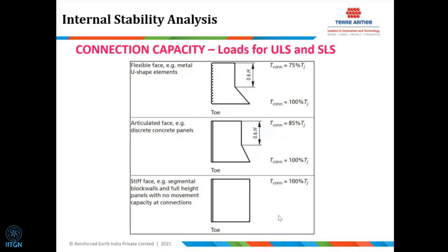because the behavior of the soil when we are doing the construction differs, as soil is not uniform around the world. The tests on which the coherent gravity method was developed, I'm sure they used a very nice soil, very good, and there is no doubt. But when we are building so many walls, are we really using the same kind of very good sand? No, it's not possible. It's not practical also. Let's be very honest and transparent.